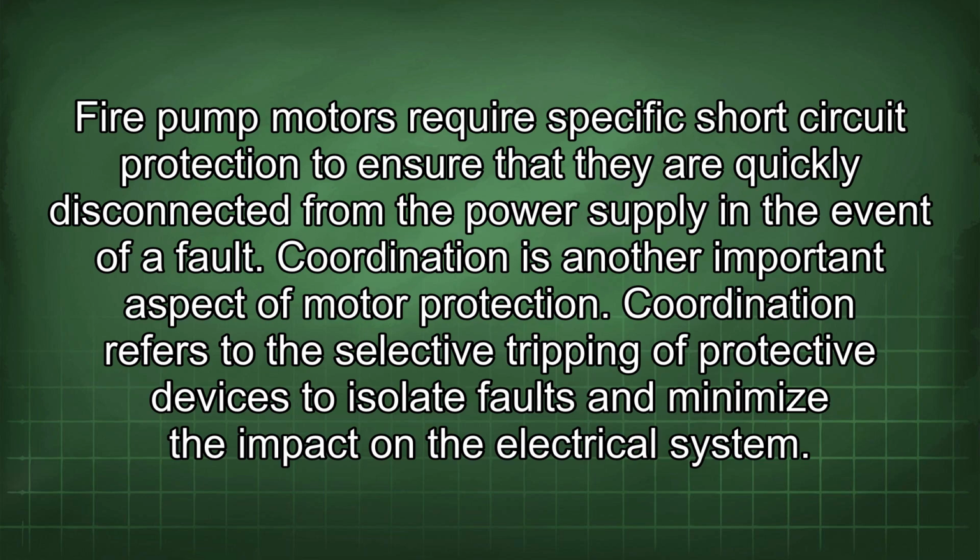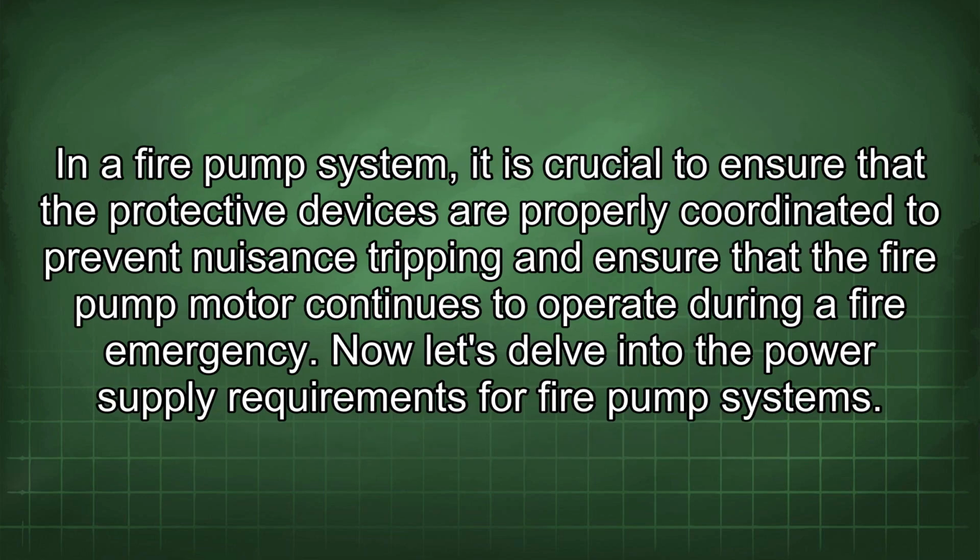Coordination is another important aspect of motor protection. Coordination refers to the selective tripping of protective devices to isolate faults and minimize the impact on the electrical system. In a fire pump system, it is crucial to ensure that the protective devices are properly coordinated to prevent nuisance tripping and ensure that the fire pump motor continues to operate during a fire emergency.